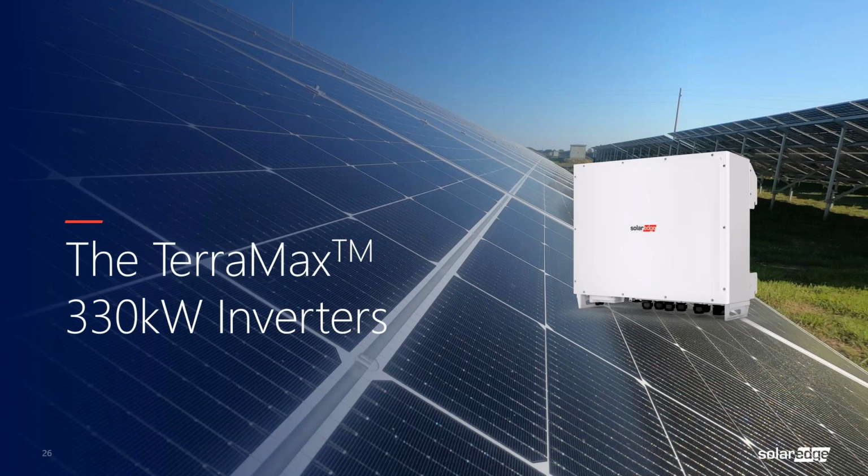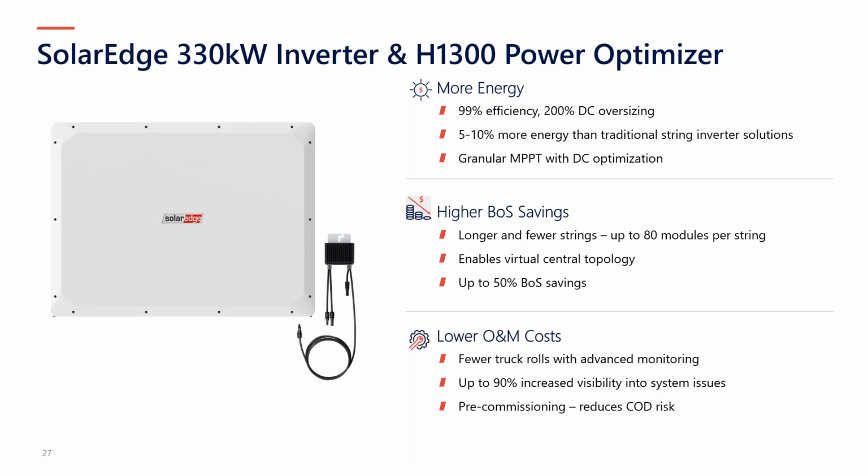Now moving on to our 1500 volt DC ground mount solution. We call that the TerraMax. It's a 330 kW inverter. It's not modular. It's one big unit. And one thing to note is it's paired with our H series optimizers. So it does not pair with the S series. It's only paired with the H series.